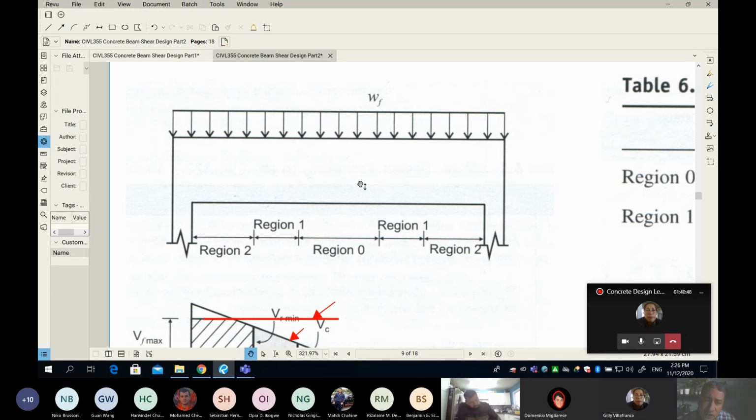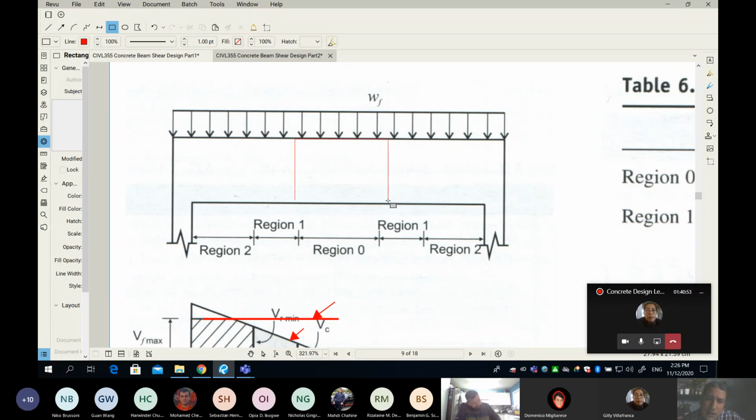And then after this zone here, which maybe I'm gonna make a square here, maybe this zone doesn't need stirrup at all because concrete is good and it can do it on its own. I'll do some coloring. So in this zone, probably concrete is okay because the shear force is very little. So concrete can survive on its own, no need for stirrup. But as we go from the center to the support, what happens to the shear force? It increases. And because it increases, then maybe it will go above what concrete can handle, and at some point we will start to need some stirrups.